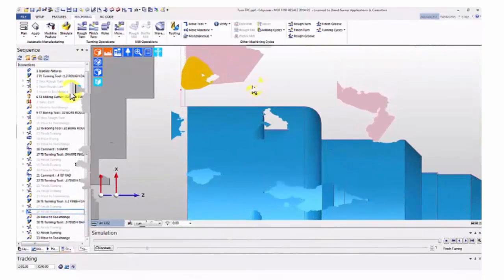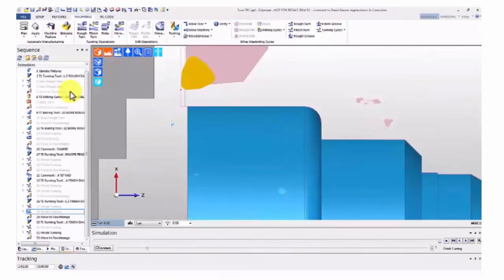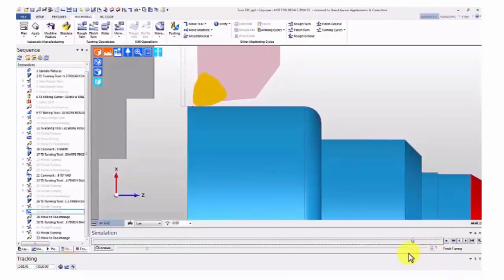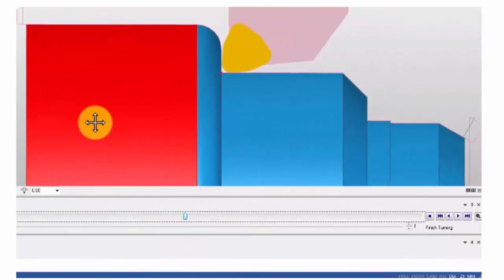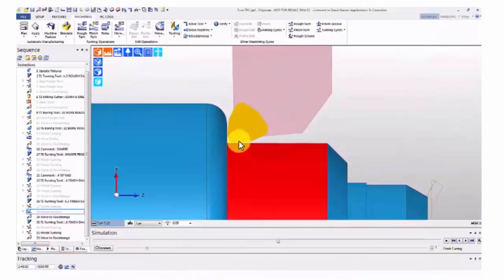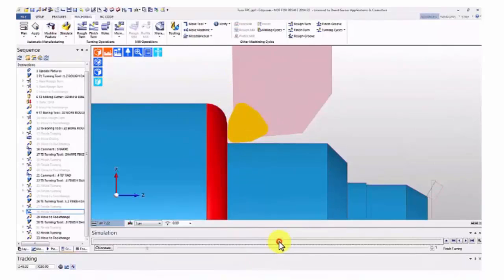You may have heard people talk about look ahead in CNC programs. Well, the reason why we have look ahead is because sometimes the control needs to know what's going on in front. And tool nose radius compensation is where this applies, because once you have put this into tool nose radius compensation, it's constantly got to work out a path which puts the tool ready for the next position. Because if, for example, you look at this tool, and this is why I put this exaggerated radius on it, so that you can see it's got to go up here now. It's going up this path up there.